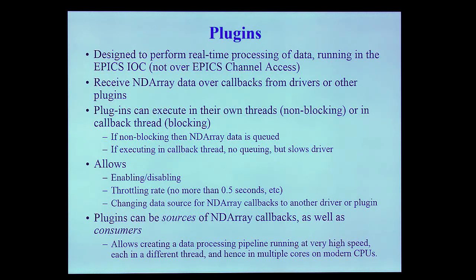Okay, I'm going to move on to plugins. Let me just see how I'm doing for time here. Plugins are designed to do this real-time processing of the data. They run in the EPICS IOC. As I said, they receive their data from callbacks from the drivers or other plugins. And an important thing is that they can execute in their own threads. That's called non-blocking mode. Or they can execute in the callback thread.